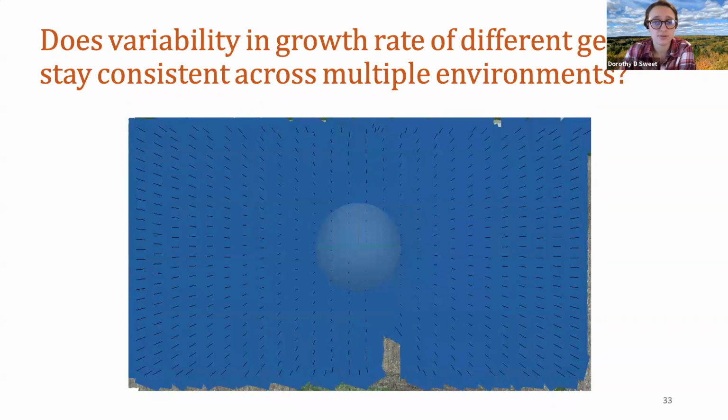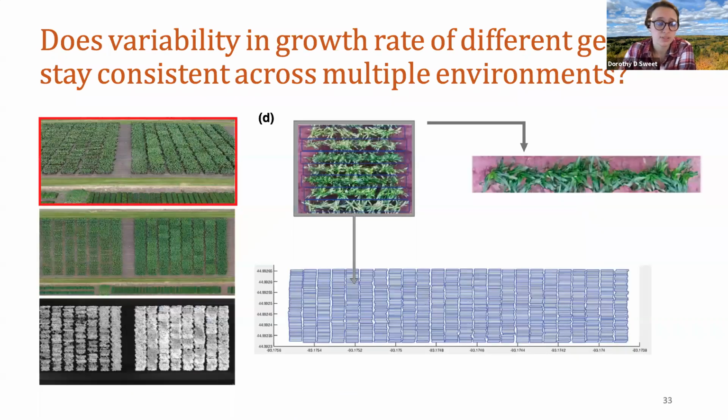So from these aligned photos, a dense point cloud, which is a 3D image of the field, an orthomosaic, which is a compiled aerial image of the field, and a digital elevation model, which shows elevation differences, can be formed. From these data, each single plot can be identified by a bounding box and extracted, and then plant height and canopy coverage can be pulled from that image.